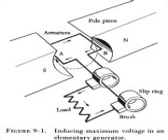Compound wound DC generators. A compound wound generator combines a series winding and a shunt winding in such a way that the characteristics of each are used to advantage. The series field coils are made of a relatively small number of turns of large copper conductor, either circular or rectangular in cross-section, and are connected in series with the armature circuit.